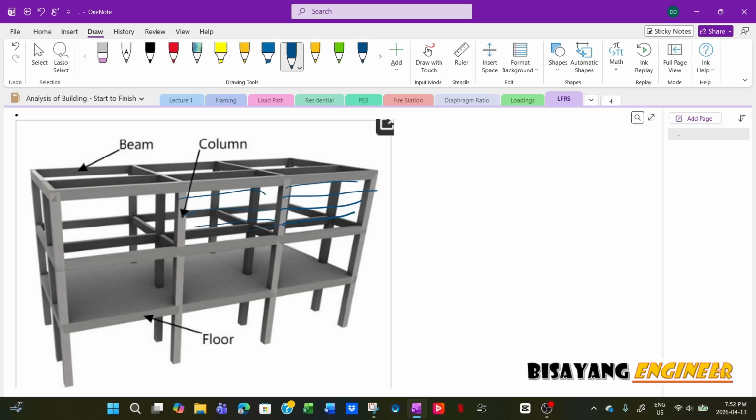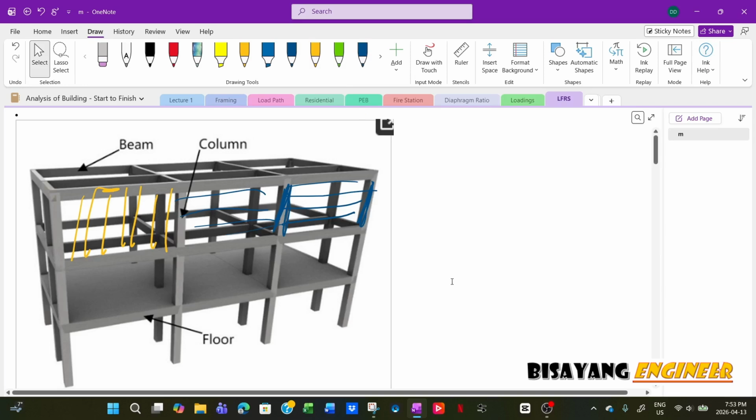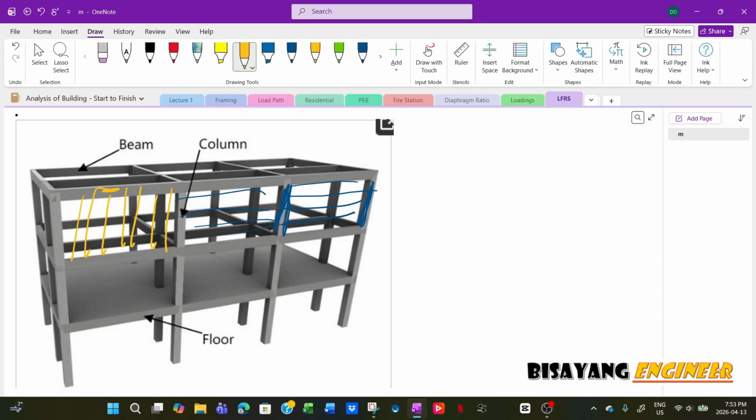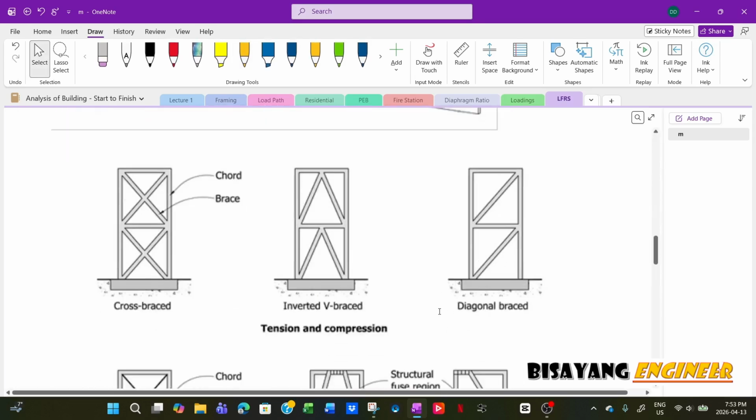Now, of course, the load will be transferred first to your column instead of the usual. If you have vertical studs, then it will be transferred to the beam. So that's why it's very important to know, when you start analyzing or modeling, how the loads are transferred to your main structural element. So if this is a steel frame where we have a metal building here.